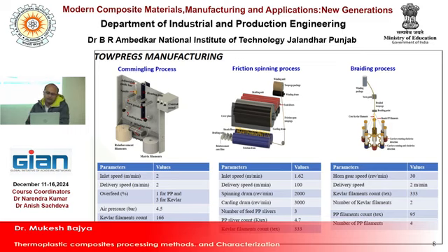In that case, the matrix is generally chosen with a low melting temperature, and whenever you are choosing the matrix, that is very important. The processing temperature of the matrix should be lower than the degradation temperature of the reinforcement filament.